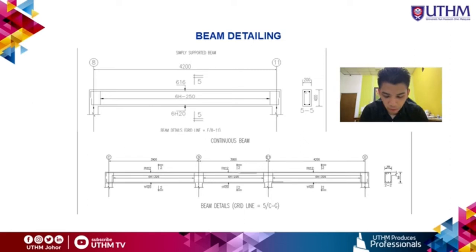The calculation is done by span member for deflection, cracking and spacing. The detailing obtained for the continuous beam is 2H12 for the tension reinforcement and 1H20 for the compression zone. The link spacing varies according to the values obtained in the calculation.